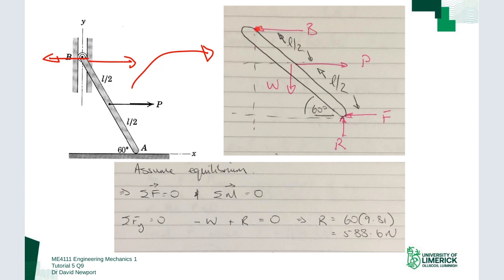Okay, and what I've done is I've indicated that B is acting in this direction. My logic for this is that P is pulling it out, so chances are that B is going to come from this surface. It's been pulled into the surface, so chances are it'll react that way, and there wouldn't be much of a reaction force there. So the net reaction force is that way. In effect, there's two because there's two contact points in the bearing, but we're just going to treat it as one combined reaction force.